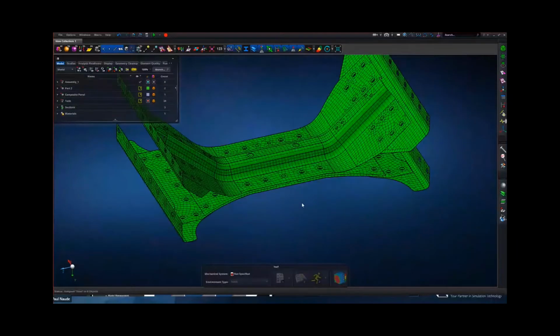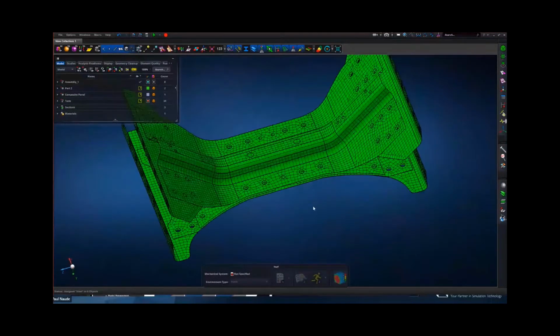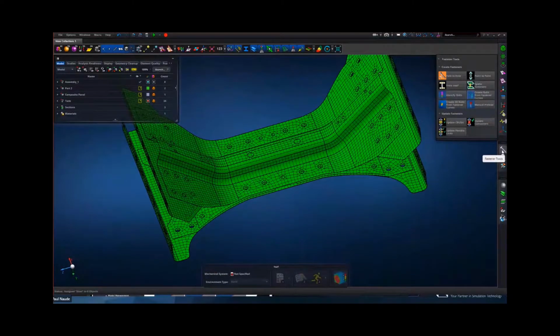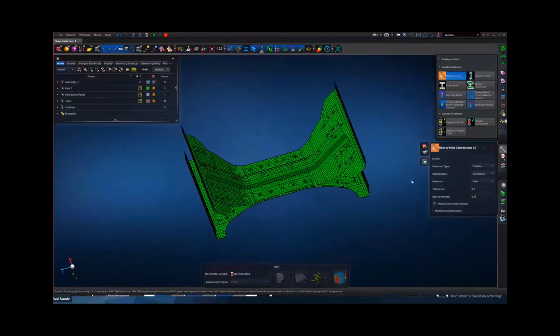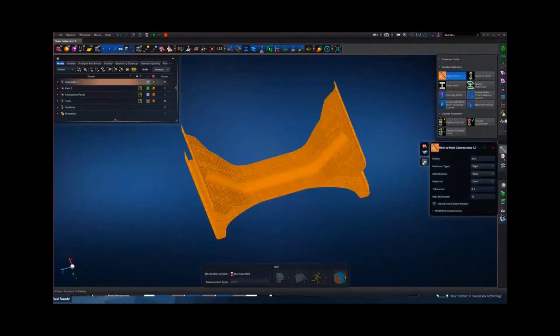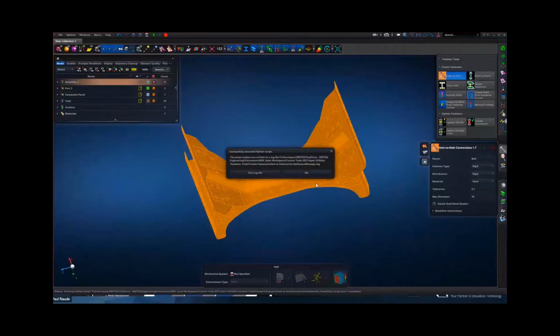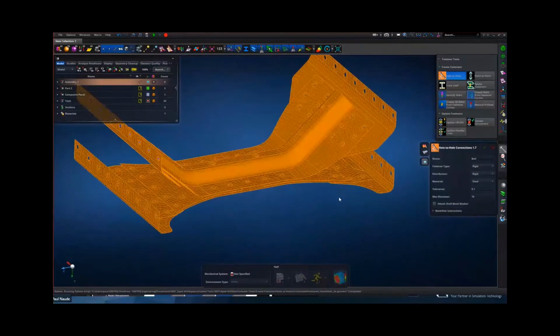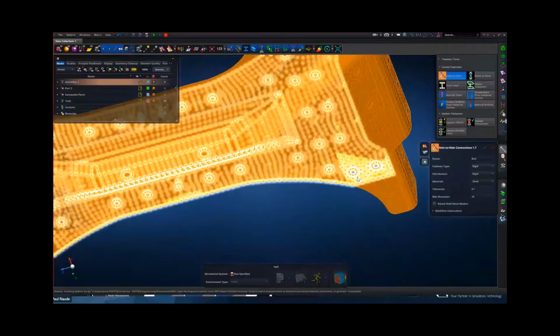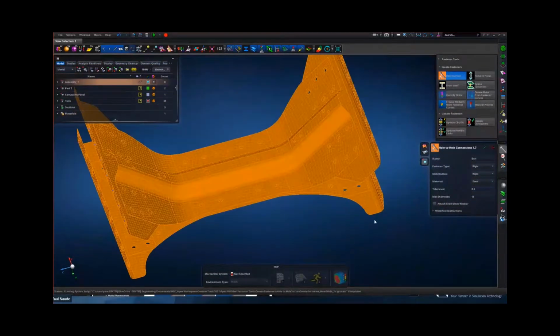And for those of you who use a lot of bolt connections, you might like this little script that comes with your latest installations. It's a script that Larry Pierce wrote, one of the pro Apex users. It's actually accessible through the Python coding. You can simply select setup settings over here, define everything that you want connected. It automatically goes and finds all the holes for you, and it creates connectors between the different plates.